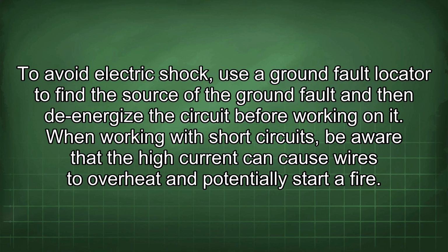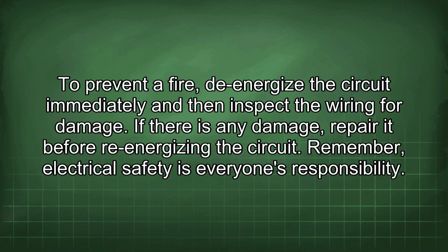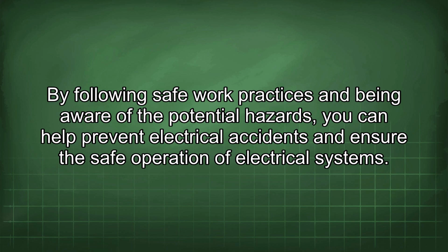When working with short circuits, be aware that the high current can cause wires to overheat and potentially start a fire. To prevent a fire, de-energize the circuit immediately and then inspect the wiring for damage. If there is any damage, repair it before re-energizing the circuit. Remember, electrical safety is everyone's responsibility. By following safe work practices and being aware of the potential hazards, you can help prevent electrical accidents and ensure the safe operation of electrical systems.